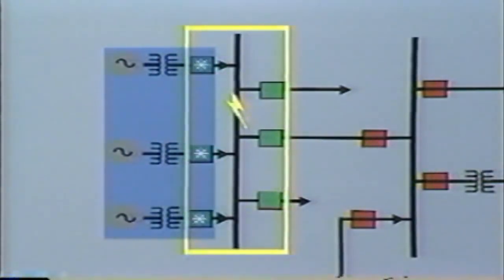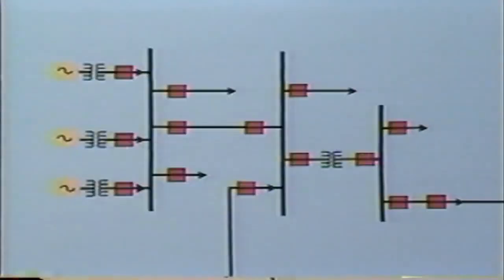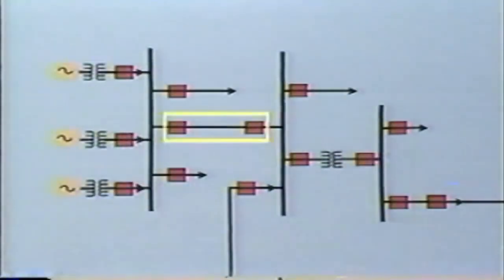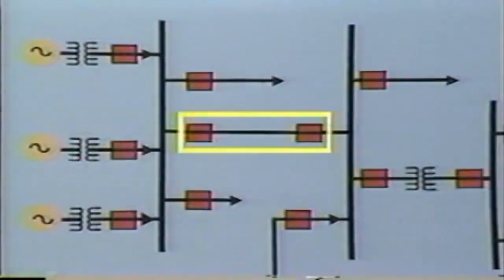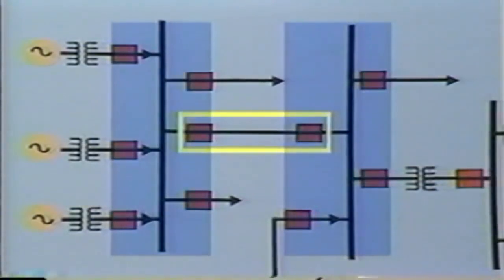You can see that these generator breakers will operate either for a fault within the generator zone or a fault in the bus zone. The next area in this particular power system is the transmission line zone, and once again, this overlaps the bus zone at either end. Hence, these breakers will open for a line fault and also for a fault on its respective bus.